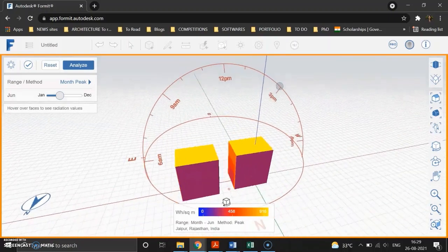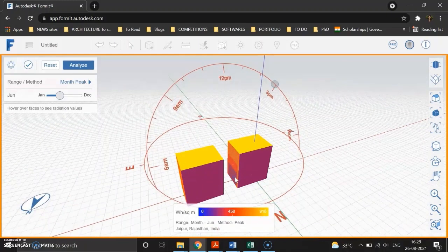Here you could see the effect of shading: at the topmost level, where the shading is towards the end of the day, it's 587, which is the highest in the east face. Then in the center it's slightly lower, 472 compared to 500 in the above part, and the lower part, which is shaded for most of the day, is around 282.4 watt-hour per square meter.